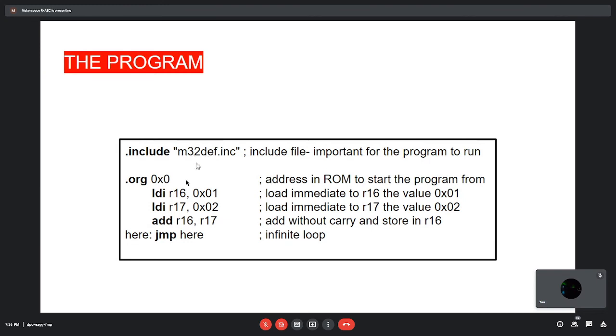If it were a 328 here, it would be 328def.inc. Next we have the .org 0x00. So .org is for originate. The entire program is stored in the ROM, the read-only memory, which is the kind of memory where the program is stored. You can say where the program should start from, the origination. I have given .org 0x00, but you can give any number, as long as it falls within the size of the memory.